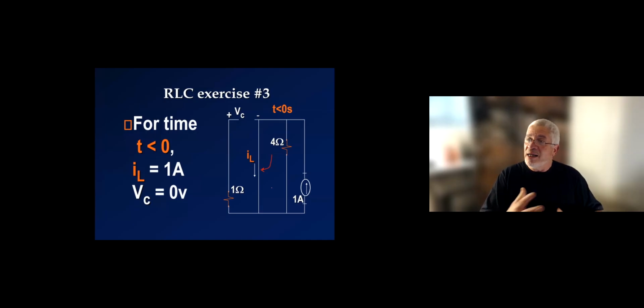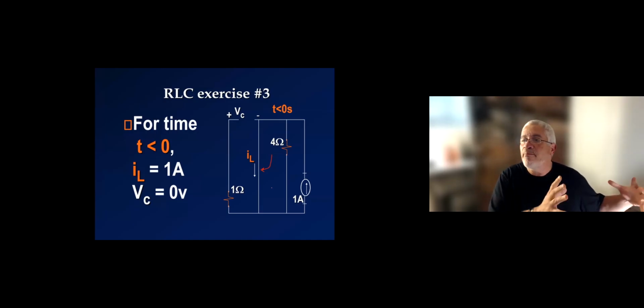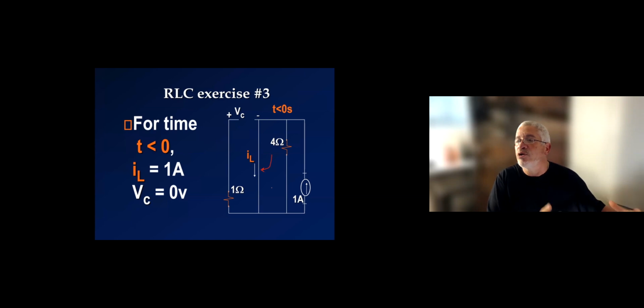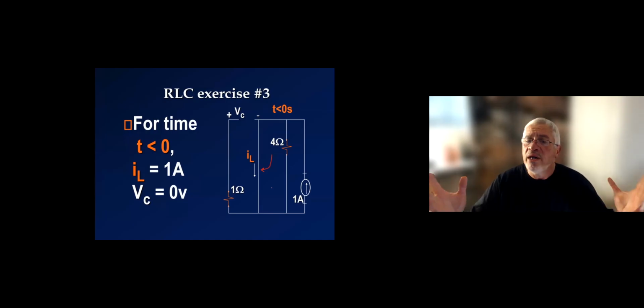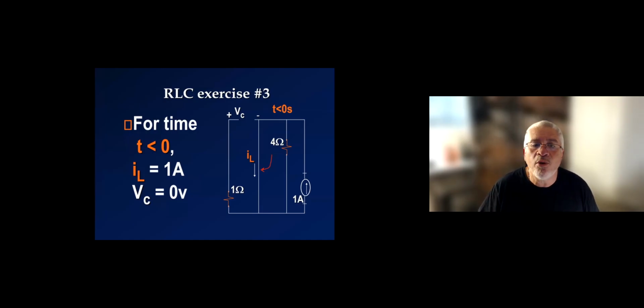Typically in the second order circuit, much like in the first order circuit, the first time period is a time period where you should not have a capacitor or an inductor acting in the circuit, because these circuits are excited by DC sources until the switch causes a change in the circuit, which happens at t equals 0. So it's fairly simple.